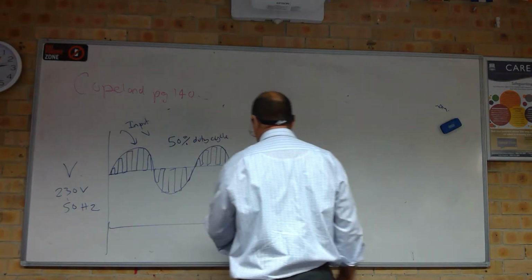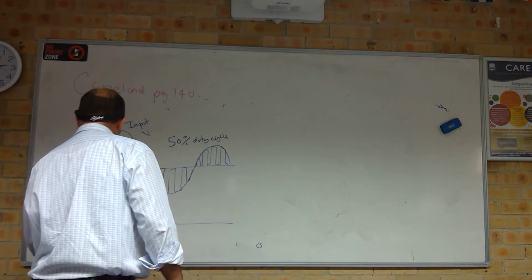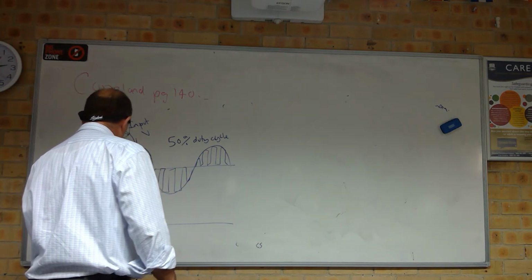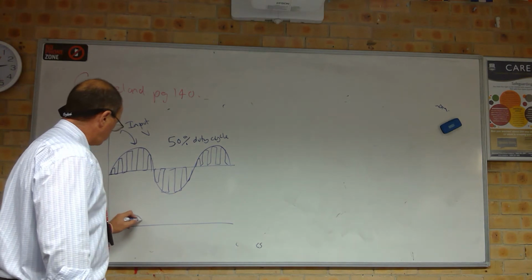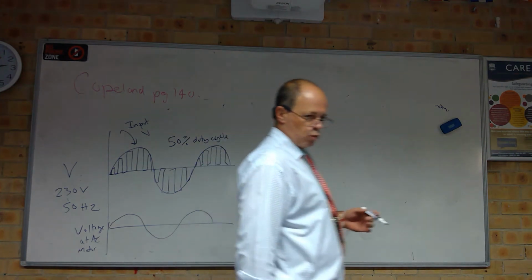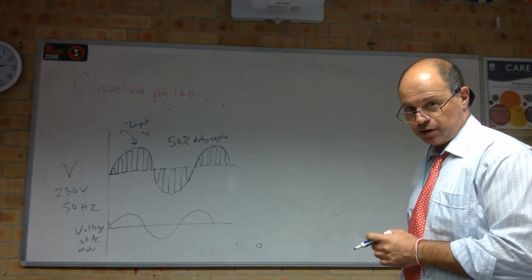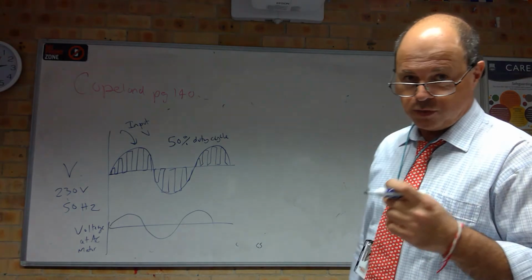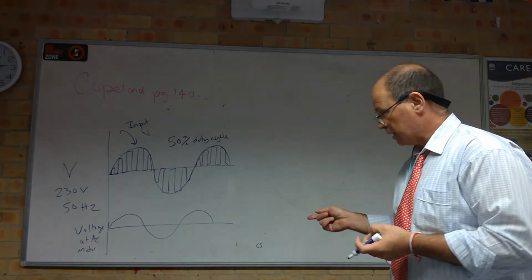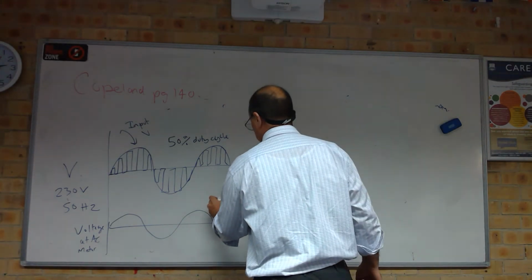So our voltage at the AC motor will effectively become a smaller amplitude because of that duty cycle. What effect do we have with the voltage? With the voltage for an AC motor, with the DC motor, when you change the voltage, you change the speed. With this particular AC situation, changing the voltage gives you less torque.